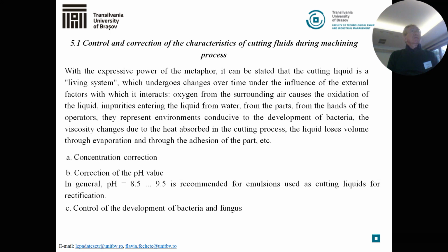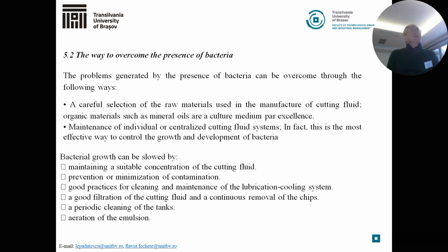In general, pH between 8.5 and 9.5 is recommended for emulsion use in cutting liquid for rectification. Control of the development of bacteria and fungus. The way to overcome the presence of bacteria: the problem generated by the presence of bacteria can be overcome in the following ways.